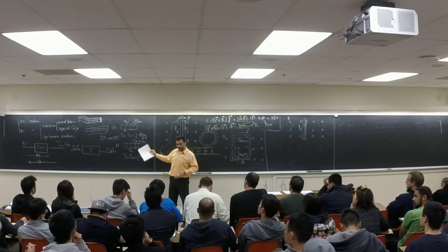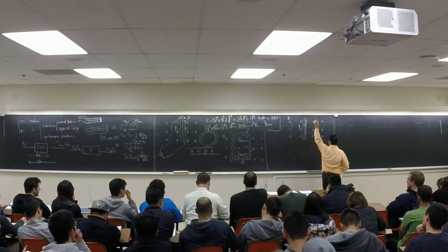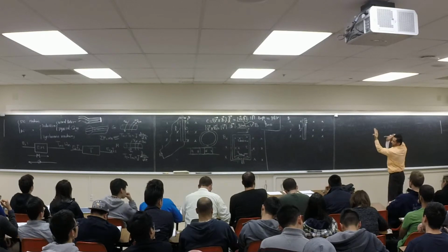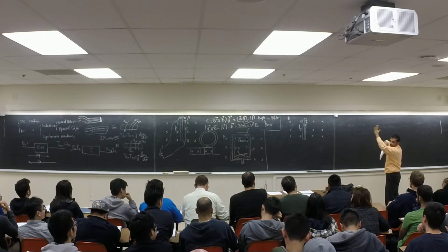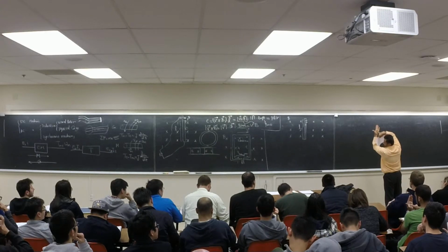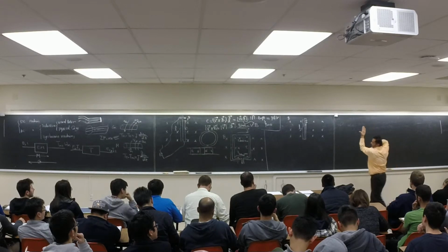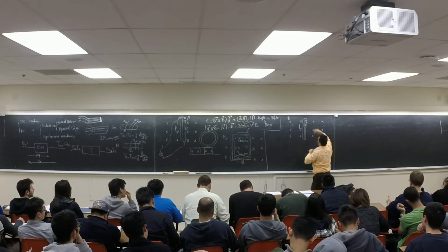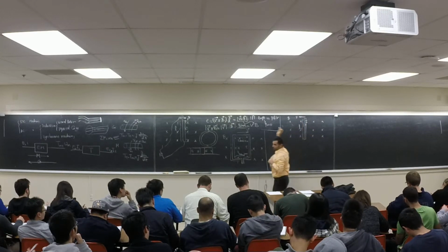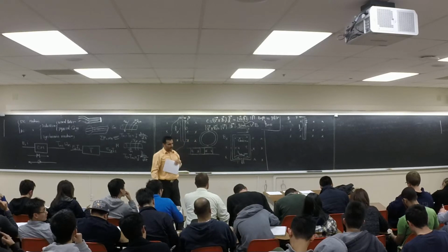Okay, the speed. Yeah. So now, here we have a current this way. We have a magnetic field this way. I use my left hand. The magnetic field goes into my hand, and the forefinger shows the current direction. So the force is going to be this way. This is the force. Basically, this conductor is going to move this way. If you have something like this, the conductor is going to move that way.